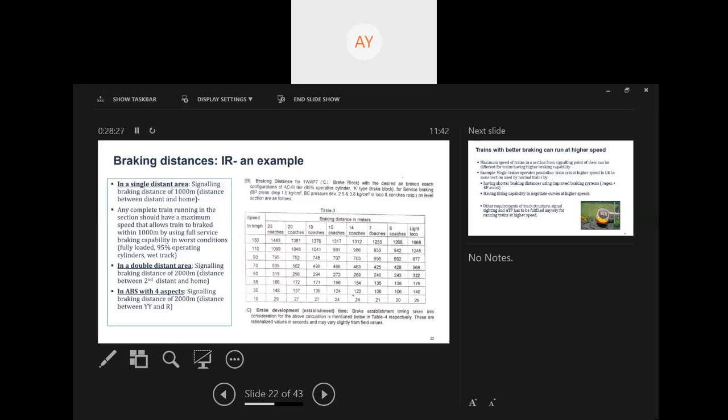If you want to get a braking distance, of course, RDSO has a rolling stock directorate where they have the simulation tool. They also have the brake lab where they've simulated a lot of cylinders of a goods train and passenger train, and they can arrive at these braking distances in a theoretical manner. But if you take these parameters from the RDSO directorate, you will see that they will always ask to undertake actual field trials to validate this. Some of these validated things are also available with them.